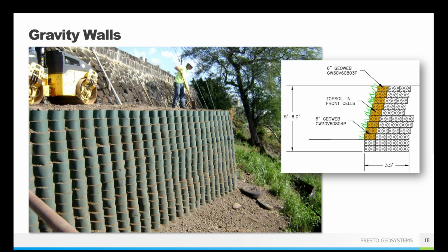You can also have a gravity style wall that is steeper or taller than 8 feet. That's again really project dependent, but more than happy to talk to you about it. So gravity walls, like I said, don't require any sort of geosynthetic reinforcement, which are typically something like a geogrid, tiebacks, rock anchors, something like that, that help hold everything in place.